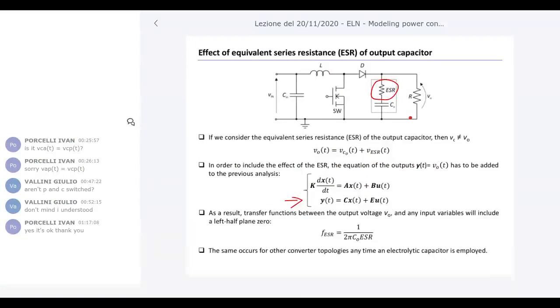They consider the fact that in a switch mode power converter the time variant behavior is not due to any component, but just due to specific elements that are the switches. The switches, with their behaviors composed of situations in which they are on and other situations in which they are off, induce a time variant behavior.